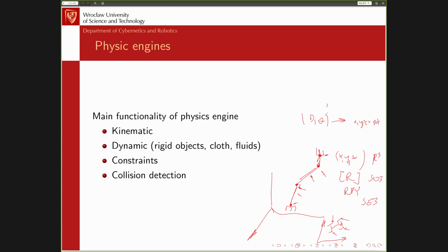So this is the transformation from dimensions and angles to, eventually, we can also have translational joints, not only rotational, so we can also translate, we can move it. So there is a mapping between the positions and angles of the joints to the position and angles of the end effector.